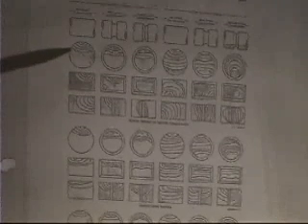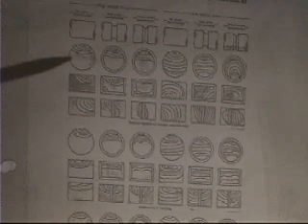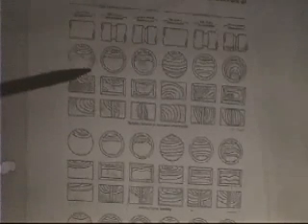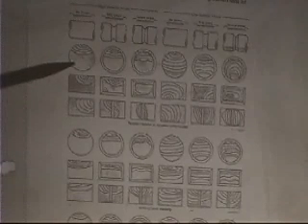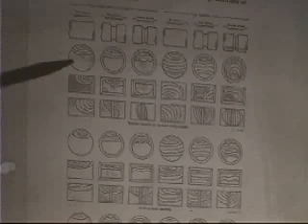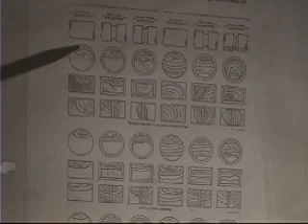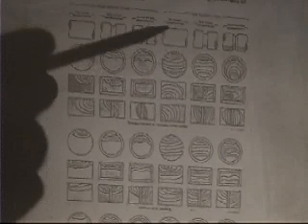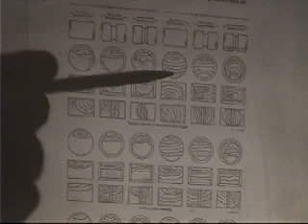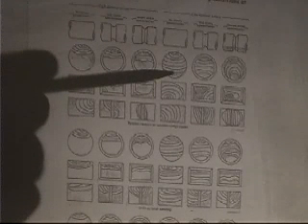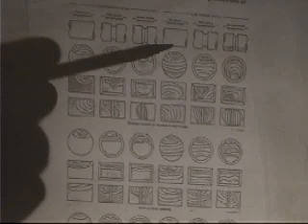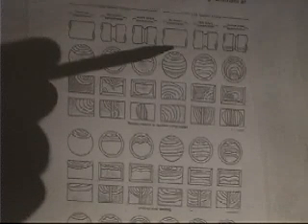First of all, I told you at the last class that typically you won't get fatigue unless you're above about half of the yield strength of the material. Well, this is high nominal stress. The final fracture is greater than half of the sample, so the nominal stress was probably greater than half of the yield strength of the material. And so you can expect a fatigue crack to start there. But how can I explain a crack starting here with no stress concentration but low final fracture? Because this is maybe only 20% of the final cross-section. How did that fatigue crack initiate? They're not supposed to initiate if you've only got 20% of the stress.